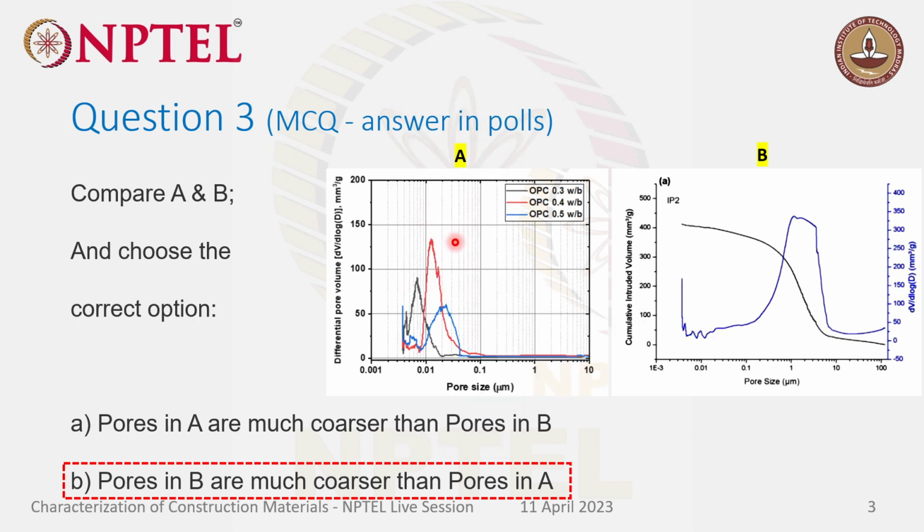So from a cement system we can't expect such kind of behavior. When it comes to historic structures, mostly it's masonry structures, brick masonry or stone masonry. There will be a unit, and above and below the unit there will be a mortar to bind it together. Usually they consider the binder to be the weaker part, and the brick should not fail. The mortar can fail. So they work in that perspective.